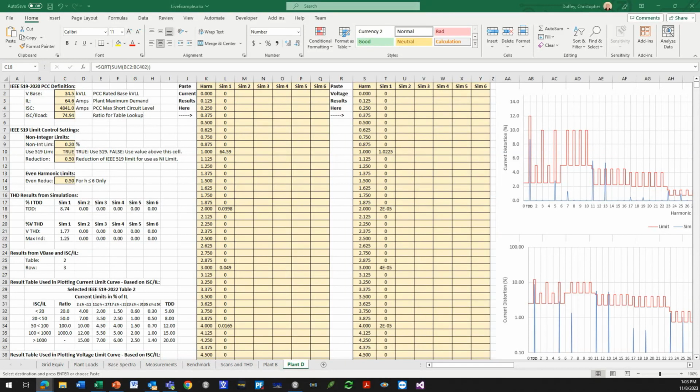If you were to filter out at the loads, the actual loads, you would find yourself spending more money. But you would find yourself releasing capacity on the downstream equipment. So let's say the distortion is pretty high and the harmonic content flowing through the upstream transformer is maybe causing some heating. Well, you may want to filter down low because you want to reduce heating in the transformer. And then also you're going to get some power factor correction out of it. And if you get that out of it downstream, you may release some capacity in the transformer that's upstream.